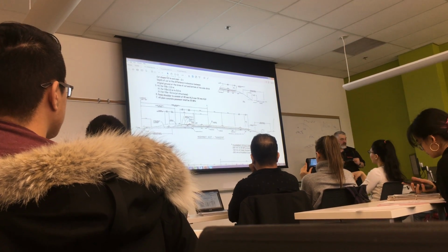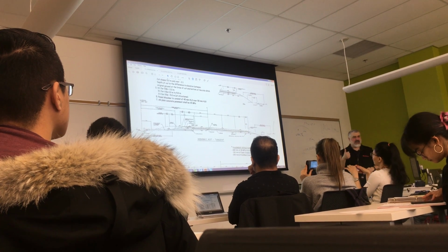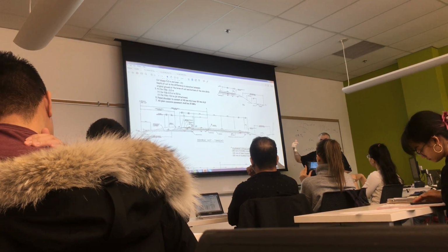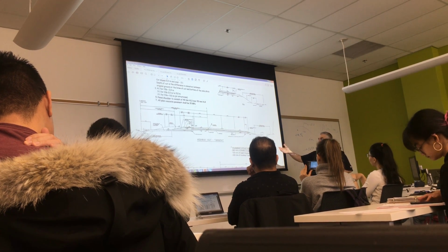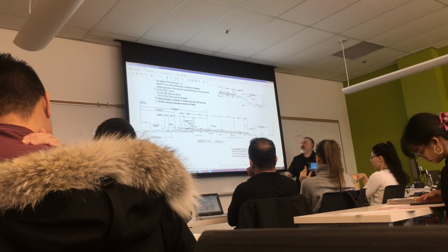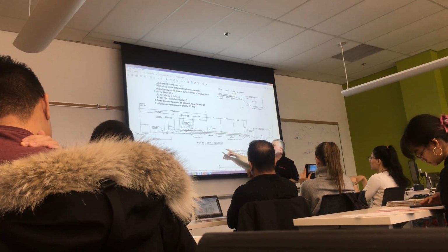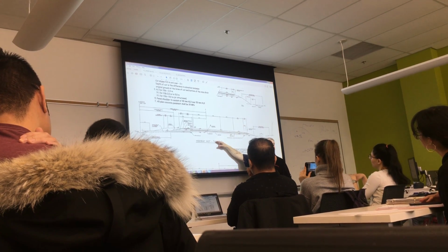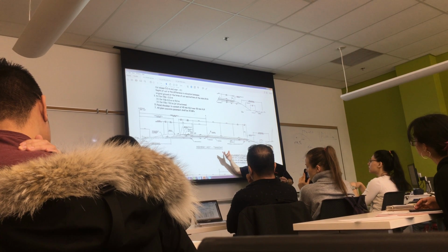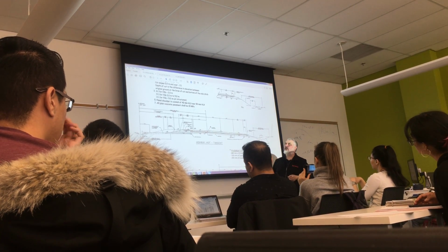So there's an example of a couple of cross sections, just to use as a guide. It doesn't have to be in color. I don't care about hatching. Just draw the line work and dimension everything. Label the slopes, label the widths, label everything that's important. Tell me what it is. In this case, the name of the section will be the station, 4 plus 650. Don't just draw a section. Where is it? 4 plus 650. What's the pavement thickness, and so on. So this is all the information you need to show.